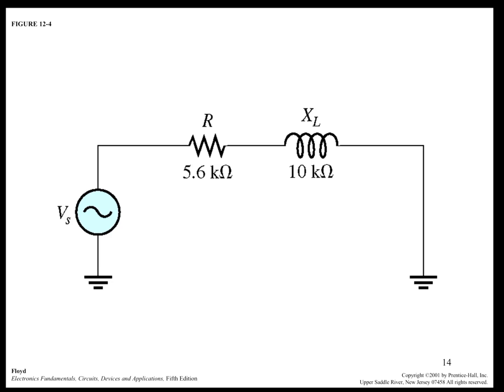Okay, so if we look at this example, first thing we need to understand in approaching total impedance here is that we're working with a series circuit. That's important because we have to kind of back up for a minute and not get clouded by these details, and remember that when you're talking about a series circuit, that's when you can add oppositions directly in order to come up with total opposition.